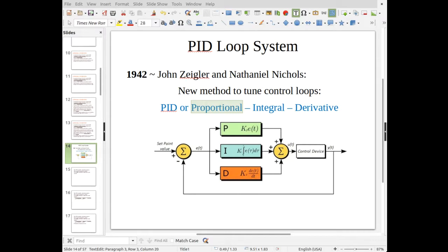All right, so if your PLC has enough processing power to do everything, not just your PID controller, but you might be doing 3 or 4, 8 or 10 PID control loops with one PLC. Can it do all of that with the delta t that you're giving it? Okay, and various aspects like that. So the speed of your controller and how fast the system itself is going to respond.